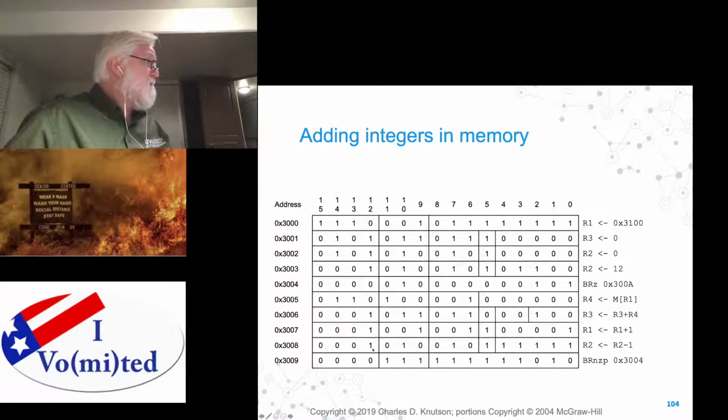So there's add, there's R2 source, immediate value, 5 ones. If that's a 5-bit 2's complement number, that is -1, my friends. So this is contents of R2 minus 1. It just adds those together and puts the result back into R2, and then we do an absolute jump.